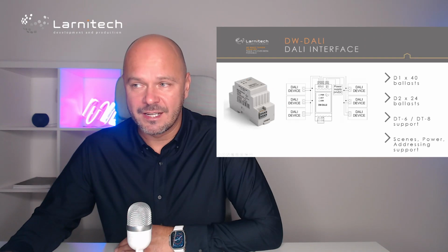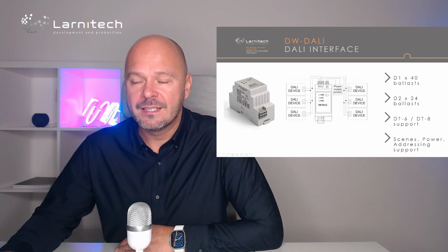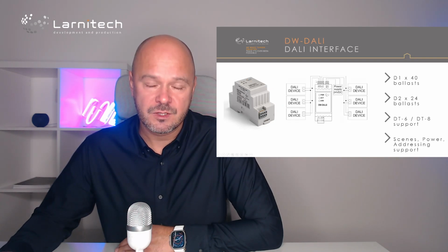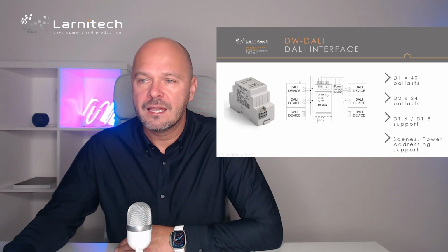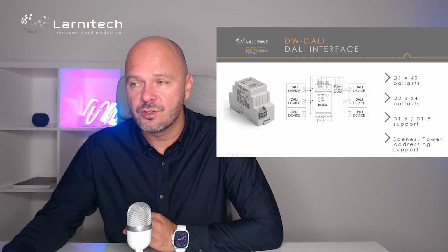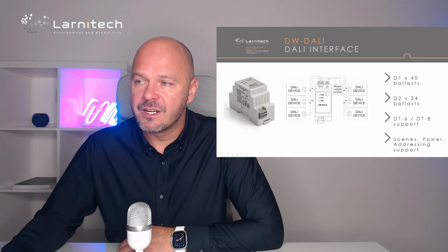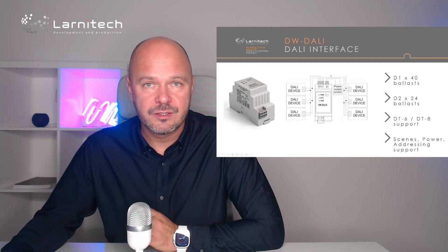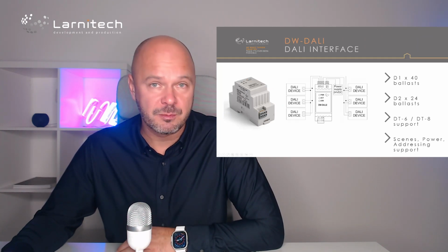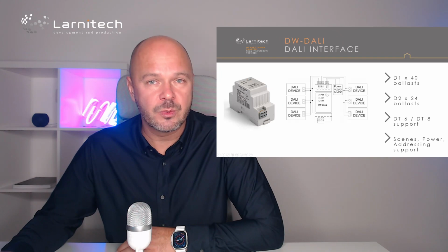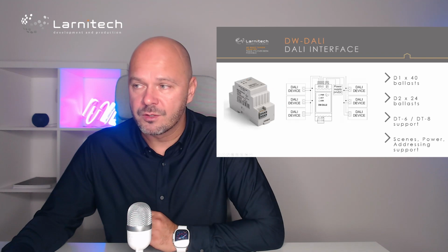Up to 40 DALI devices can go to the first connection, and up to 24 to the second connection. So 40 plus 24 is 64. You cannot connect all 64 to one input, so keep this in mind. This device also gives power to the DALI network, and you don't need a special DALI power supply. You will just need a normal 24 volts power supply, and you power the DALI network.